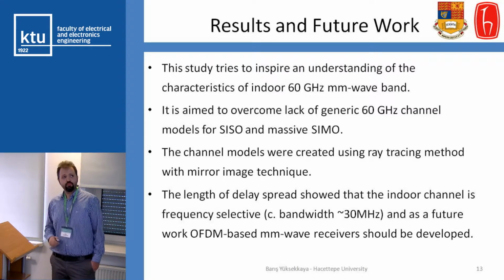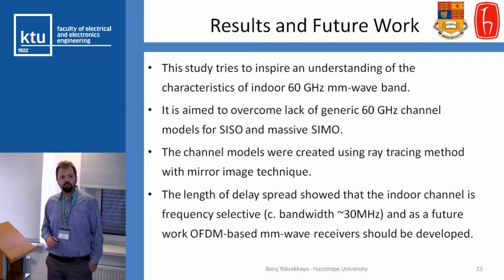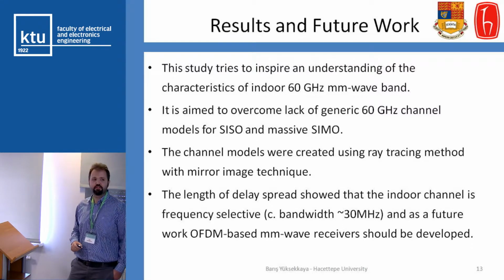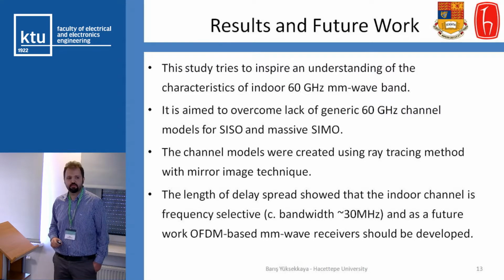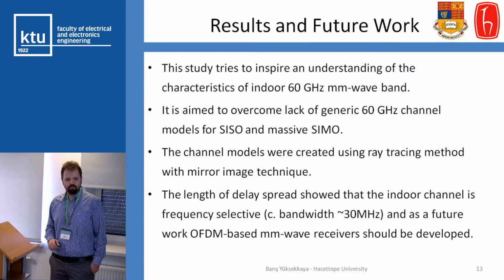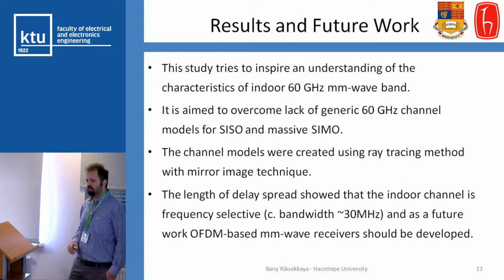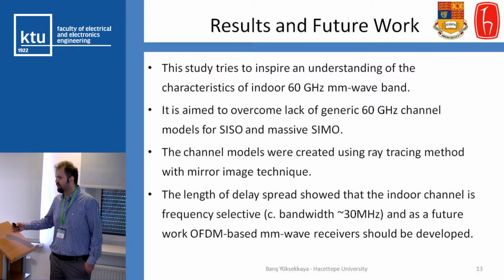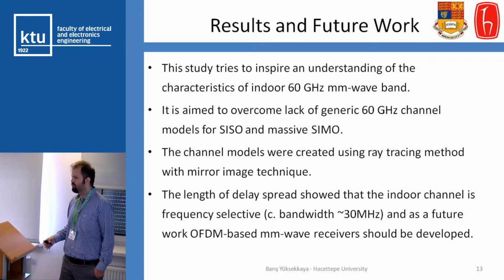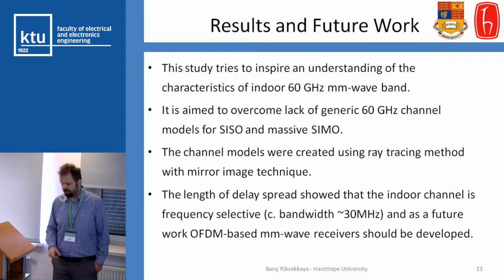To sum up, this study tries to inspire an understanding of the characteristics of the indoor 60 GHz millimeter wave band. I have aimed to overcome the lack of generic 60 GHz channel models for SISO and massive SIMO. The channel models were created using a ray tracing method with the mirror image technique. And we found that the length of the delay spread showed that the channels are frequency selective. So our next work should be working on equalization techniques for millimeter wave bands, and also maybe considering orthogonal transmission again in here.